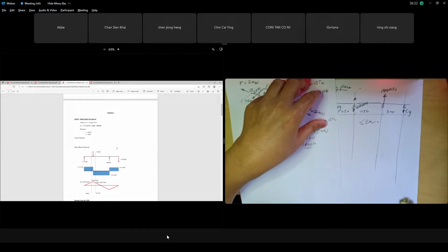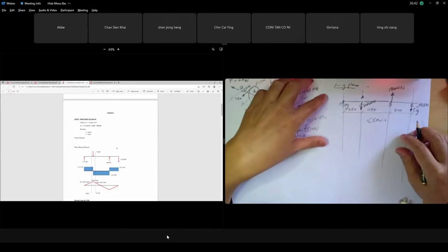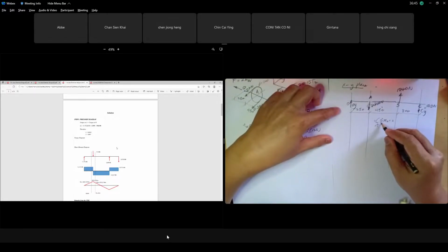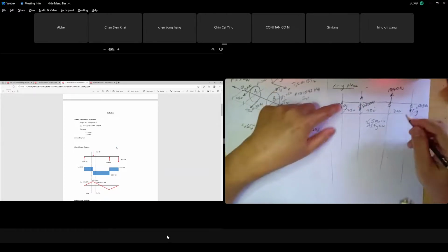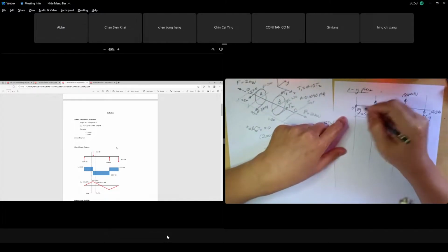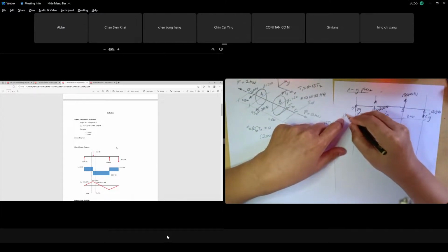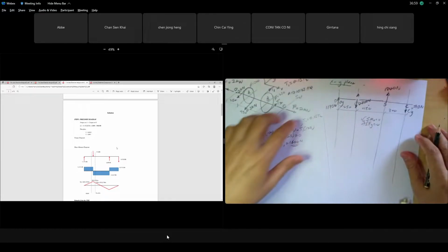The CY will be 713 Newton downward, memang downward. And you buat Fy equal to 0, then you got your Oy. Your Oy value is 1173 Newton. So you can solve it lah. Itu cara dia lah.